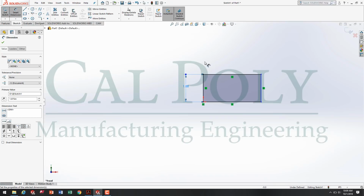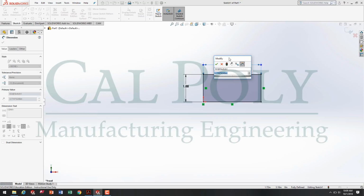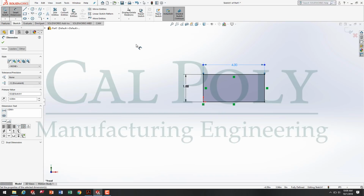Next, we need to specify the width. So we drag a dimension up and type in 4.00, check mark. So far, we've created a 1.875 by 4.000 inch rectangle.